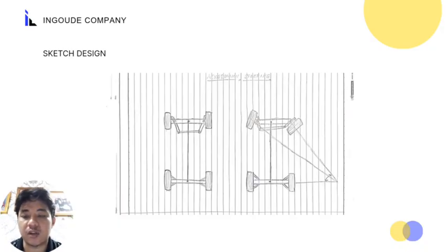We focus on material and structural enhancement for a lightweight and high strength alloy. We replace traditional steel linkage with carbon fiber reinforced composite or titanium to reduce unsprung mass while maintaining durability. Then we change to a modular type design. We introduce adjustable length tie rods for fine tuning, a common feature in post assembly, useful in motorsport and custom builds. So we focus on customer demand.